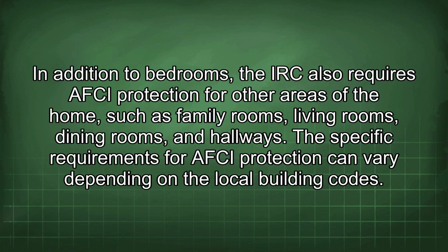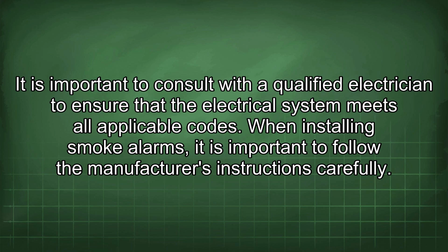In addition to bedrooms, the IRC also requires AFCI protection for other areas of the home, such as family rooms, living rooms, dining rooms, and hallways. The specific requirements for AFCI protection can vary depending on the local building codes. It is important to consult with a qualified electrician to ensure that the electrical system meets all applicable codes.